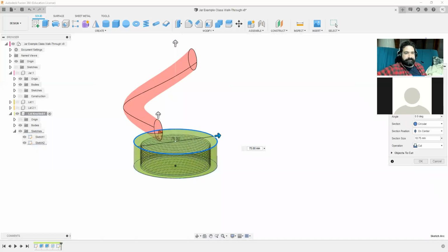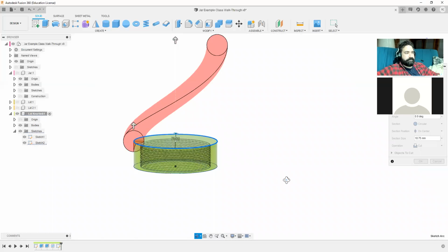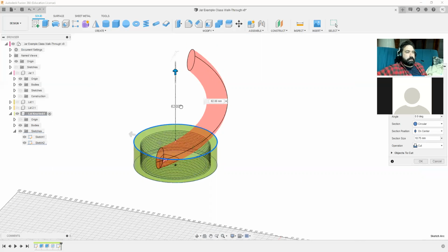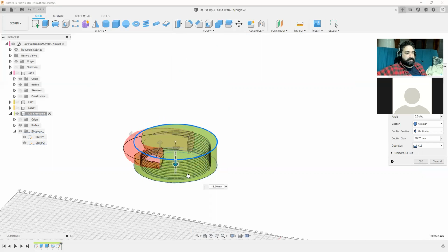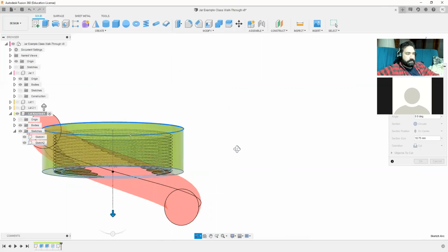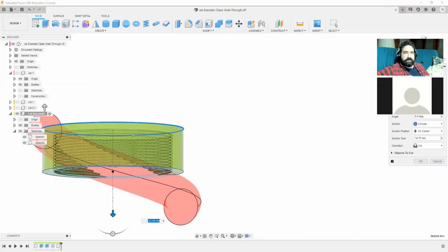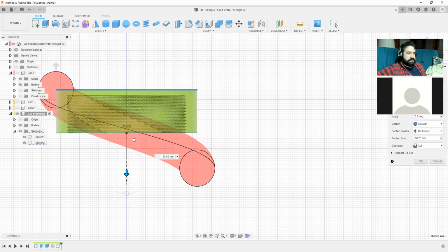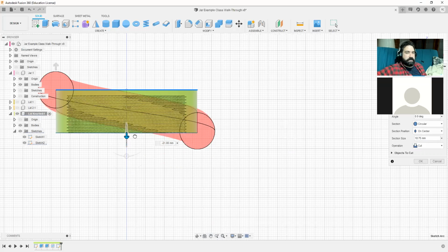For height, I'm going to use the slider for that. And I'm just tumbling around. It looks weird right now. I actually want this height to go downward. And what I'm wanting that to do is I can use the slider, keep coming up and up and up, but I also know the thing is 22 millimeters tall, so just use -22.